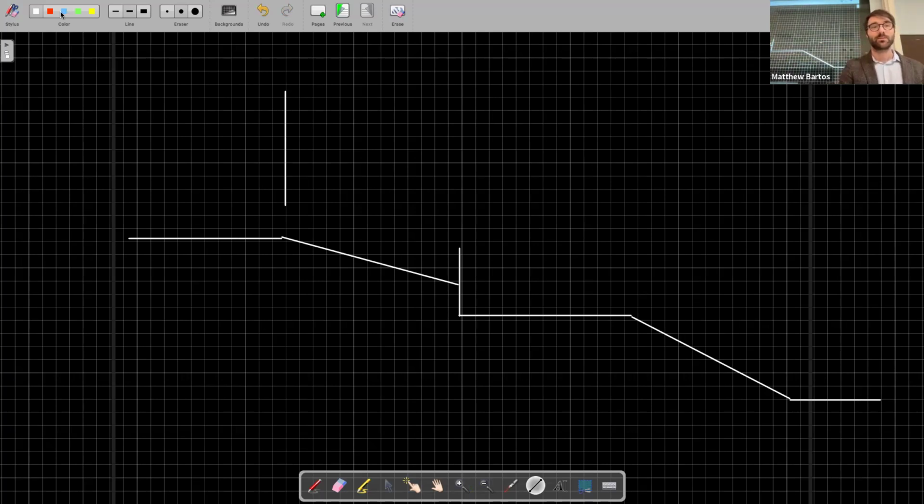So here we might have a sluice gate that is holding back water from some reservoir. So as the water passes under the sluice gate, you might get rapidly varied flow that transitions into uniform flow. At some point, it'll undergo a hydraulic jump. It'll jump up. Okay, it will discharge over a weir, which we'll also be talking about.